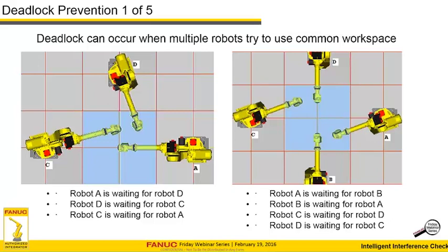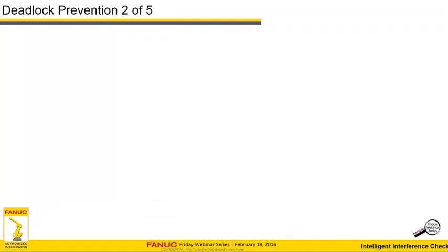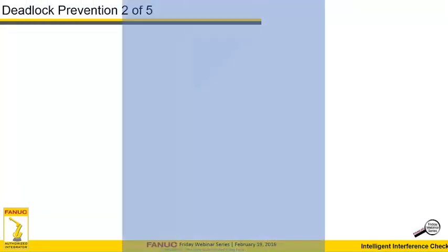And to be completely honest, programming something like this would seem like a nightmare as far as assigning zone priorities and knowing exactly where in the line in the teach-pendant program to enter the zone and when to exit the zone. So we've come up with deadlock prevention. Here's just a video of a before and after.